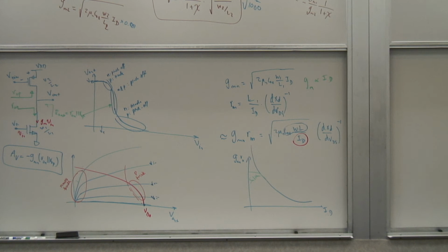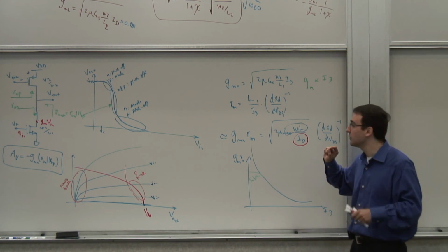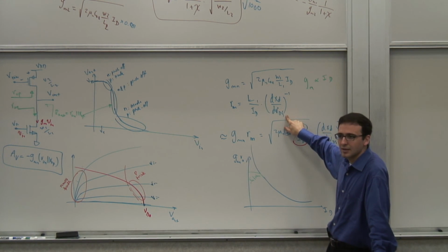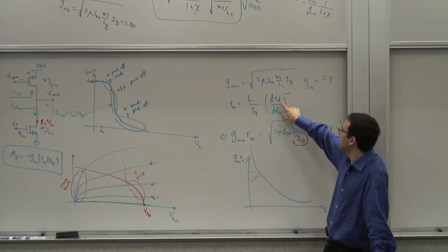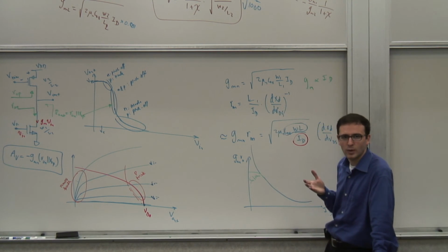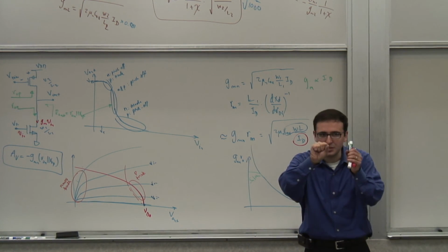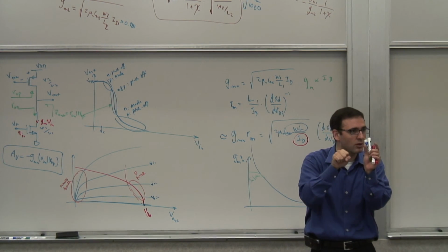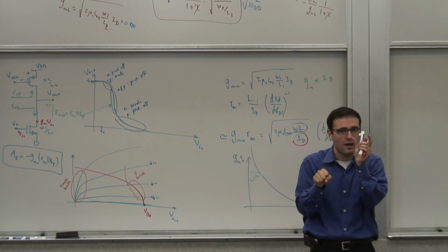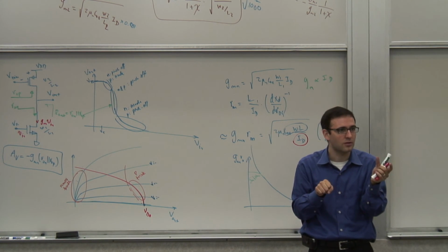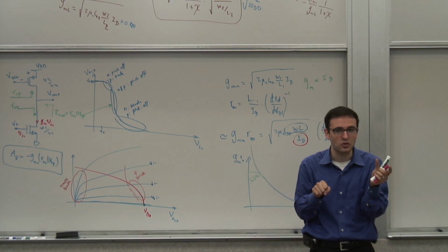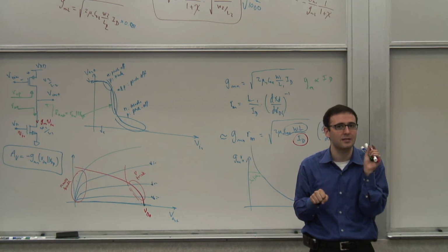Now, there's one last thing here in this equation, which is this term. If I were to change the variation of the XT versus VDS, what would I do? Well, if I make the depletion region that's formed in the pinch-off region smaller and smaller, the variations of that would also be a smaller fraction of the total channel. So one of the things I could do is to try to shrink the width of that depletion region.